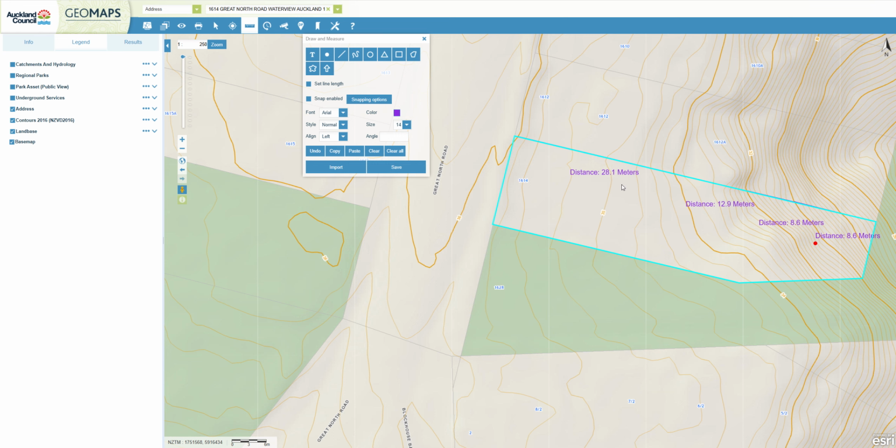So the site goes from a gentle to moderate slope, to moderately steep, to very steep towards the back of the site. So this is a mixed variable contour, so it's given us an idea of what the contour is across the site, and we'd know that this would be triggering retaining and some additional foundation costs.